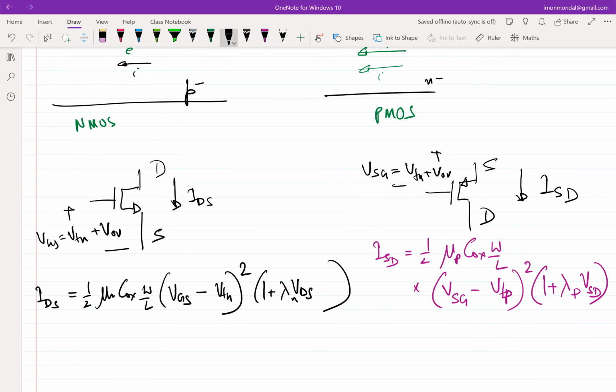So sometimes you will see that threshold voltage is mentioned as minus of something, but we will essentially ignore that, and we will say that we are always bothered about the mod of the threshold voltage because we are interested in using it in this form. We don't want to get into those negative positive business. So if you find somewhere the threshold voltage of a PMOS is minus something, you assume that is because of this flipping thing, and you take mod of that and go ahead. So in this course, we'll always use positive. Even if I mention negative, I'll say that mod of this is positive, so that we are not confused about it.